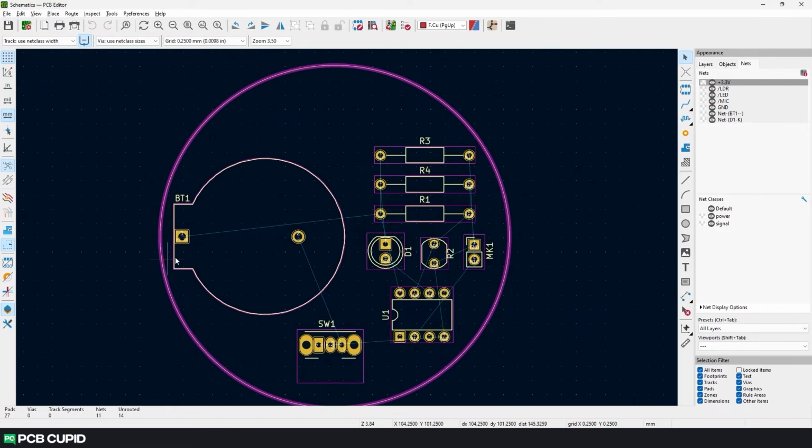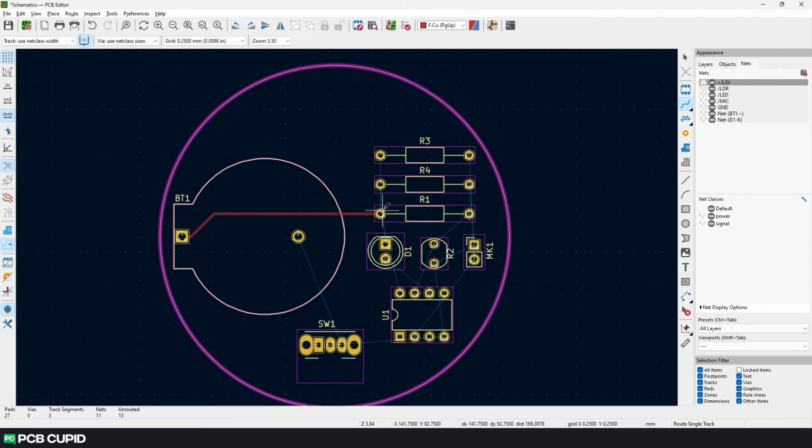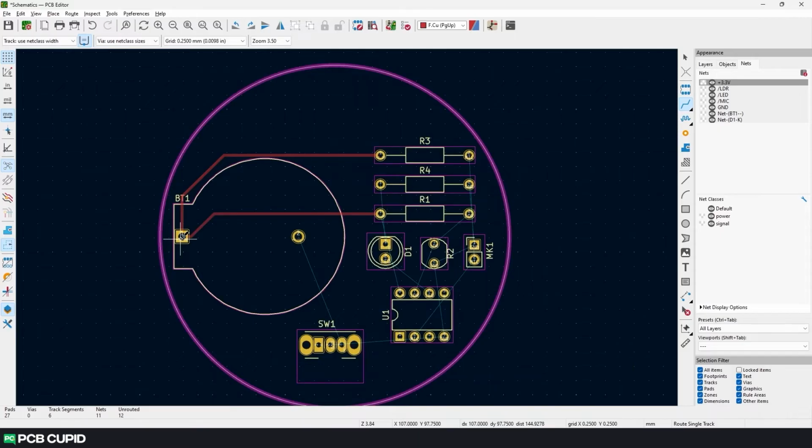Now to form the copper traces, we can use the tool that's provided by KiCad. It's called Route Tracks. Now I'll select this tool. Just select the pad and do a left click. We can see the trace follows the cursor, and also it gives us the option to end at 3 different paths. It's always recommended to choose the shortest distance. We can also do a left click while moving the track, which will lock in the position and give us more flexibility in using the track tool.